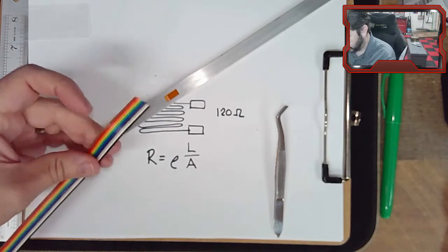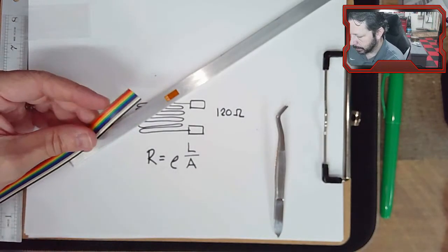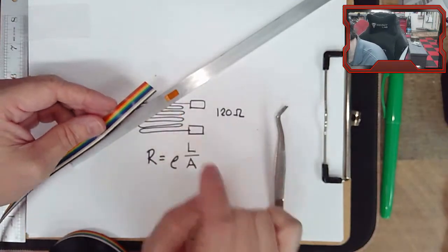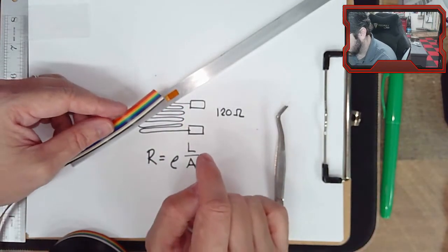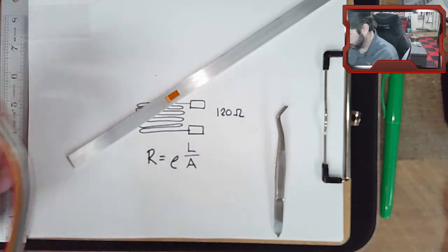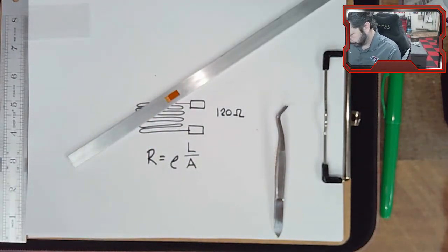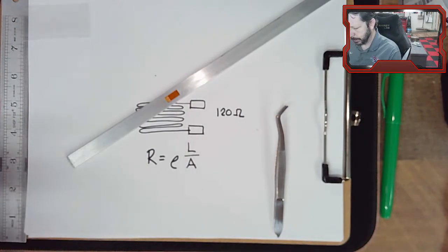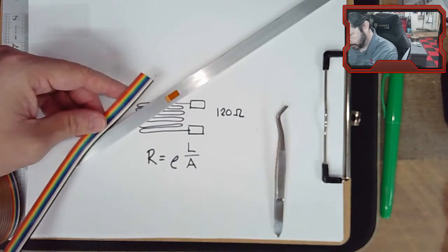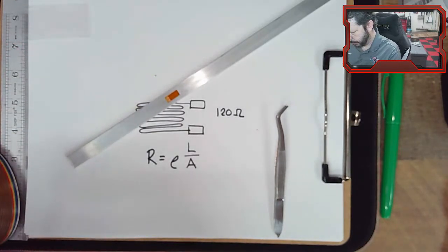I don't need all these, I only need two wires. There are different ways you can hook up strain gauges. These particular ones just have two solder points, so we're going to solder two wires. Maybe we'll do the white and black wire. And I want to leave enough length on it so that I can plug it into a circuit. So maybe I'm going to cut off something like, well, let's just peel the white and black part out.